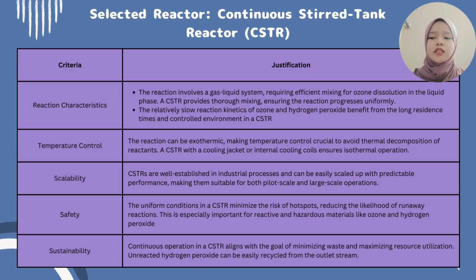Therefore, for the reaction step, we have selected a continuous stirred tank reactor, CSTR, because of the reaction characteristic, where the reaction involves a gas-liquid system that requires efficient mixing for ozone dissolution in the liquid phase. A CSTR provides thorough mixing, ensuring the reaction progresses uniformly.